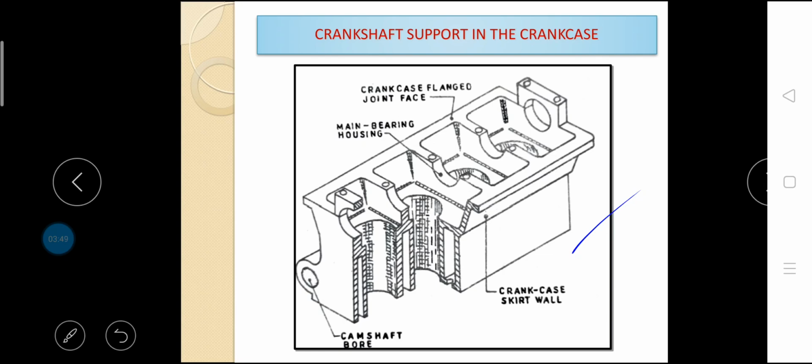Aluminium alloys have been used as an alternative cylinder block material, chiefly owing to their lightness. The density of aluminium is about 1/3 that of cast iron. However, considering the lesser strength of aluminium, which necessitates thicker sections to carry the same load, the saving in weight with aluminium alloys is only about 50% compared to cast iron. Besides this, aluminium has a higher thermal conductivity than cast iron. This results in cooler engine running, thereby making it possible to use higher compression ratios.